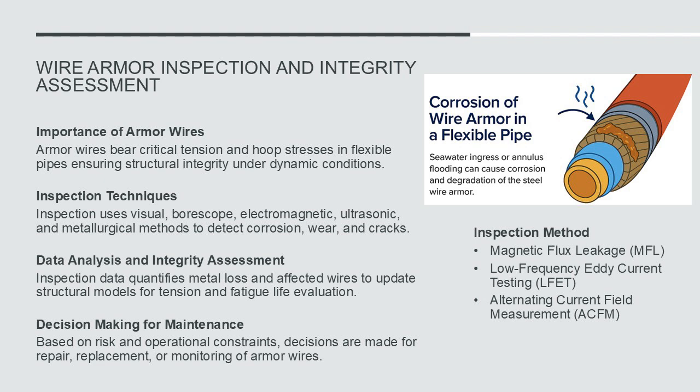Their integrity is vital for structural performance, yet they are vulnerable to corrosion, fretting, and fatigue, particularly in dynamic environments with vortex-induced vibrations, VIV. Inspection of armor wires is challenging due to limited access, but several techniques are available. Visual and borescope inspections at end fittings provide initial insights into corrosion or wear.